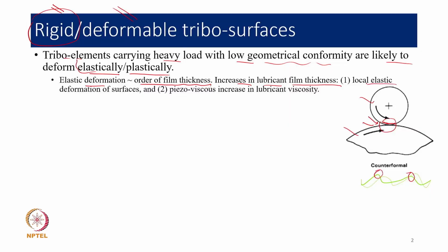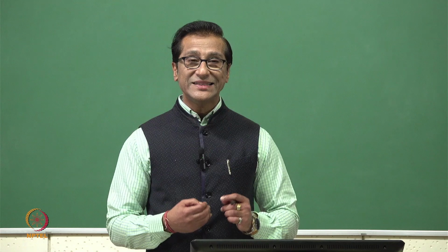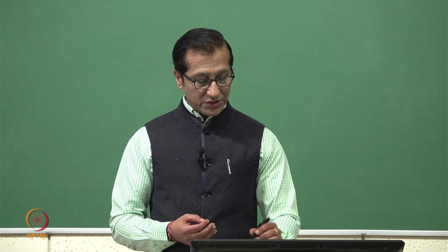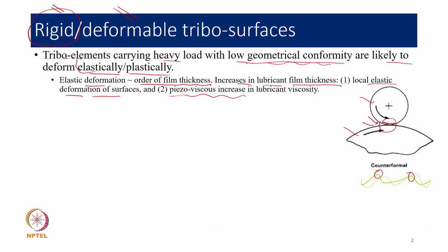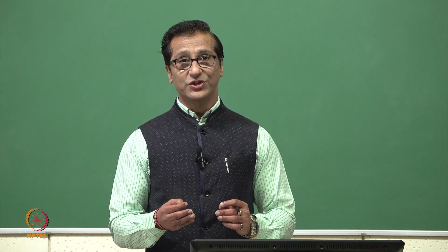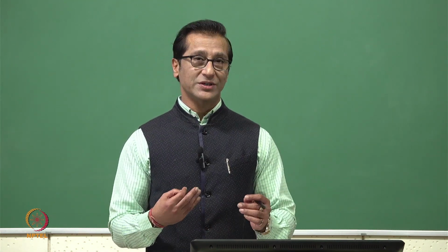That's why we say the local elastic deformation of surfaces causes an increase in the film thickness. We also learned earlier that there is a piezo-viscous effect: viscosity increases under pressure. Here, because of the low geometrical conformity, the applied pressure is very high, more than 10 megapascal. In this situation, viscosity will also increase.